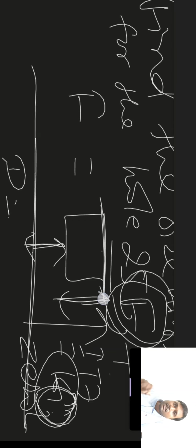So first you find I, and since it is 25, with the help of 25 you will find D, put the value of D and find I. It will come in micrometers, so convert it into millimeters and put it here. Once this value comes, we will know what the tolerance is. So this distance and this distance, if we add to the basic size, will be this much. So this will give the upper limit. In this way we can find the upper limit and lower limit.